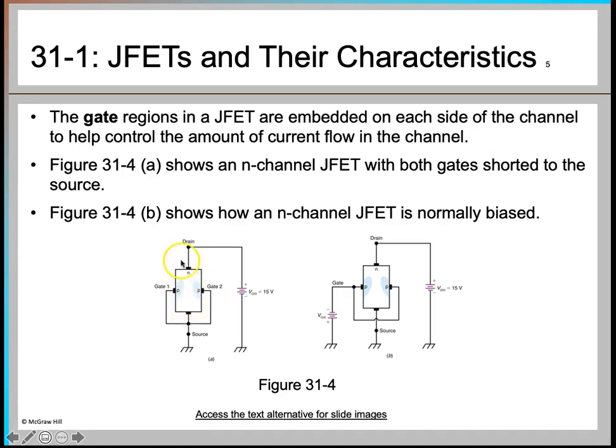If you measure the voltage across this channel, then here you are going to have stronger voltage, and here small voltage, and this small voltage is due to higher resistance. So when there is a voltage drop across the resistance, you know that it is due to the current ID. When two depletion regions touch each other, that means there is no current flowing, which means that ID equals 0. That cannot be possible because there is a drop across the resistance, and the drop across resistance is not 0, and that will be possible only if there is a reverse biased voltage applied through this.